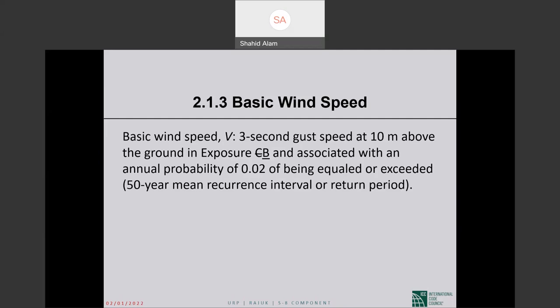I find it very difficult, we are so used to exposure C being the default exposure and so forth, to keep in mind that C is now B. Because of that, I have always kept the ASCE 7 designation crossed out and then the BNBC designation underlined. So at least I know what exposure we are talking about.